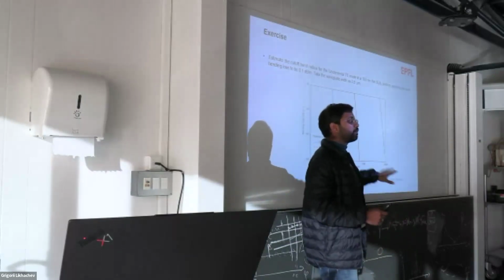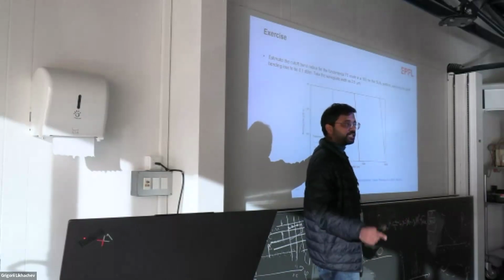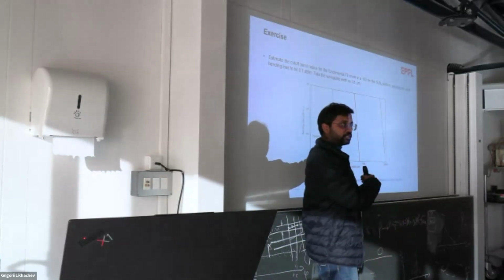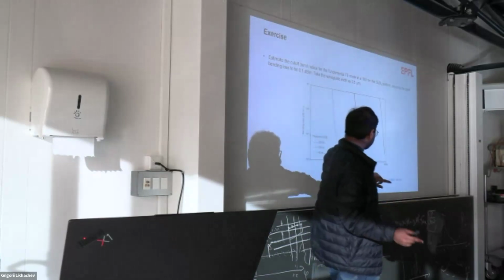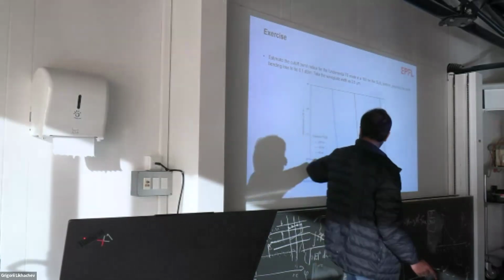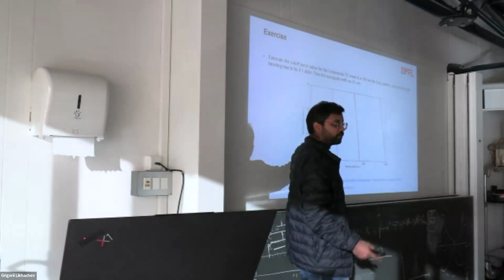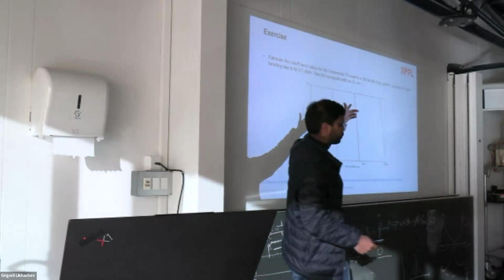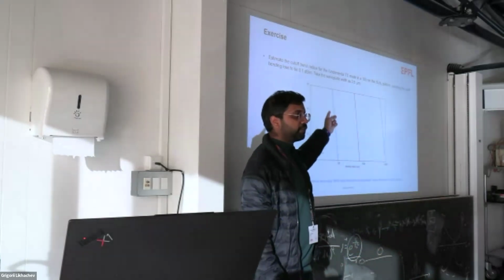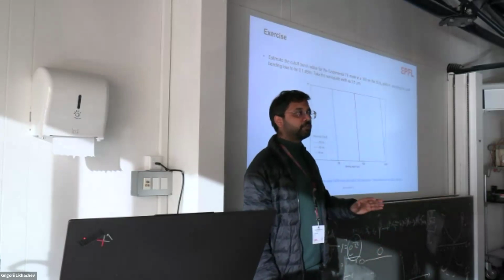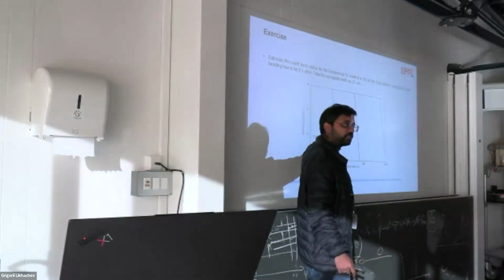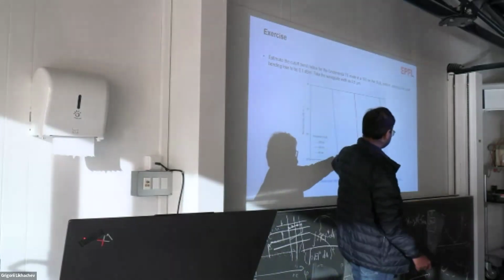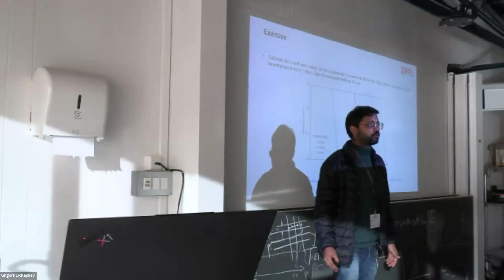So my objective was to replicate this graph, which they have put in the SI of the manuscript. So this simulation does that. What you did right now is actually this plot. I purposely changed to 200 nanometer, you can make 250. It's basically this one. And the exercise that I made was to make 100 nanometer thin, change the waveguide width to 2.8 micron and run the same simulation. Then you should get this second plot. So this is for 100 nanometer, this is for near about 200 nanometer. These two things are what you should obtain from the exercise.